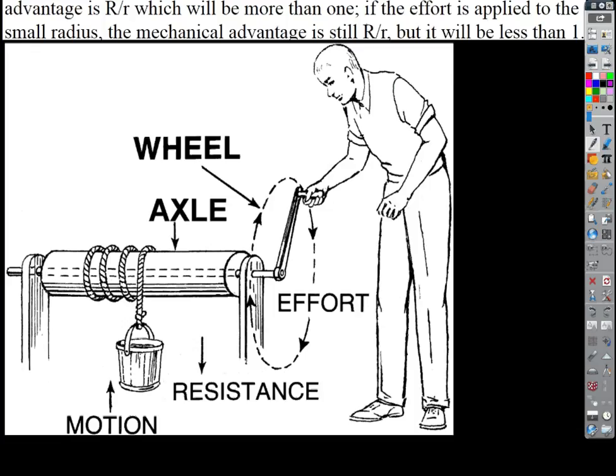Isn't that just a double wheel and axle? In that specific case, not really, because this axle right here is considered to be the part that you wrap the line around that's lifting the load or moving the load, right? And so really, this is the effective axle. It's kind of like two wheels and one axle. Yeah, but because these are rigidly attached to each other, it doesn't really matter. I mean, it would have made no difference if you had a bigger piece of wood and a bigger hole in it, right, okay? The only advantage this has is you reduce friction a little bit, okay?